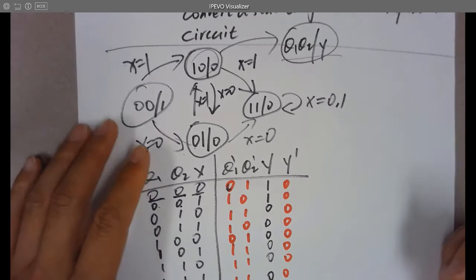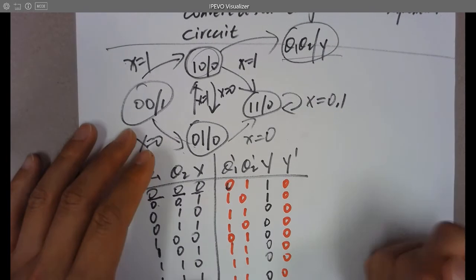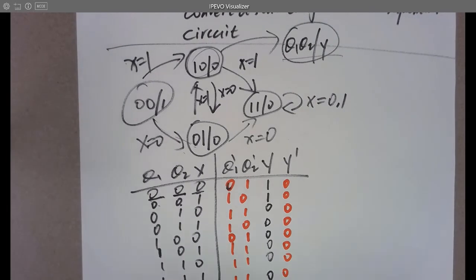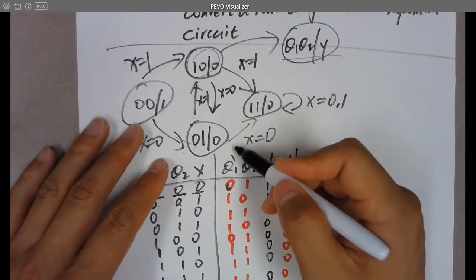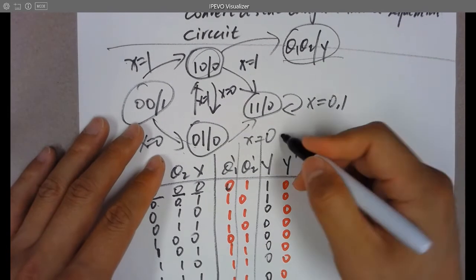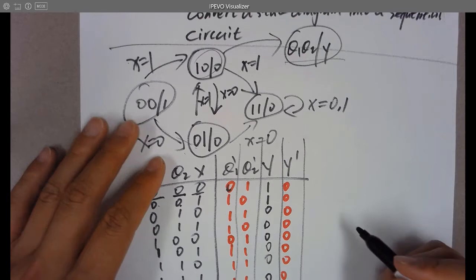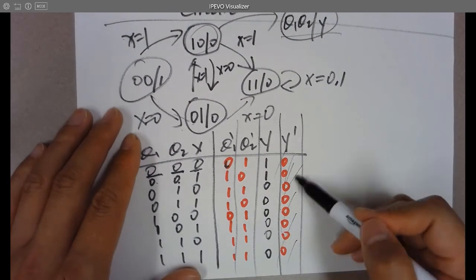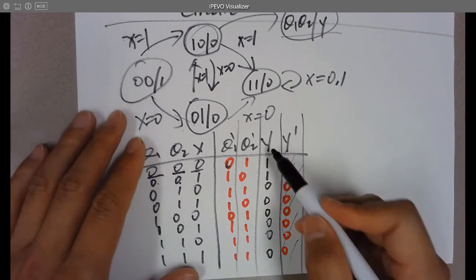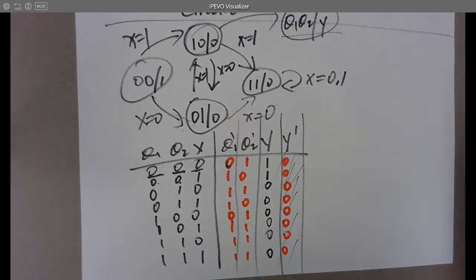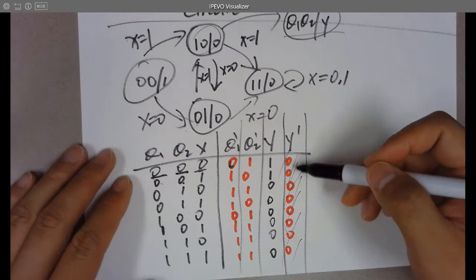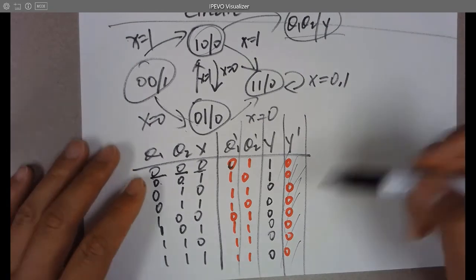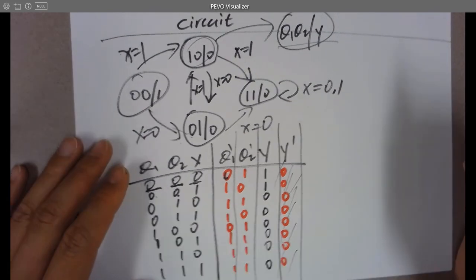And next step, we need to convert it into a circuit. Whenever we are converting a truth table into a circuit, we look at separate columns and do it one by one. But you can see that for the y prime, it's all zeros, which means you don't need it. It's totally zero, like a ground. It's always ground, so you just ignore that. Doesn't matter at all.